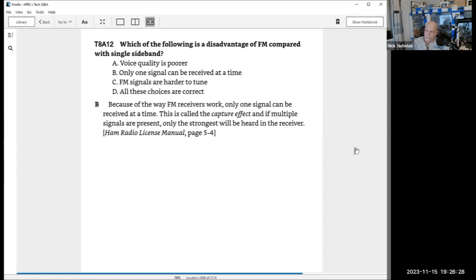The commercial aviation industry always demands that their radios be AM. And pilots have to listen to a lot of noise on those AM frequencies. They could be a lot quieter if they were FM, because they would only hear the strongest signal and it would reject everything else. And so you can turn the squelch up quite a bit and eliminate all the background noise because it would be squelched out whenever nothing's transmitting. That's what we do on FM with our FM radios.